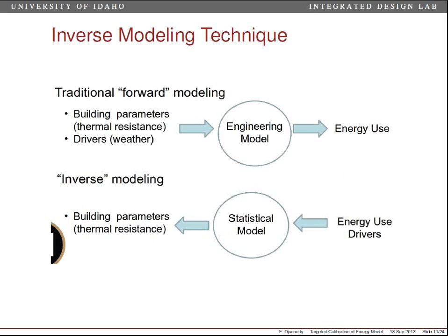All right. Moving on to the inverse modeling technique, which is the underlying method that I propose we use for calibration. Now, the inverse modeling technique is an old ASHRAE project. It's been around for a while, okay? But it's not used for calibration. So it is another modeling technique. It's just inverse, because traditionally when we say modeling, we come up with building parameters. We draw the building, we plug in the thermal parameters, and then we drive it with the weather data, and then we come up with an energy use.